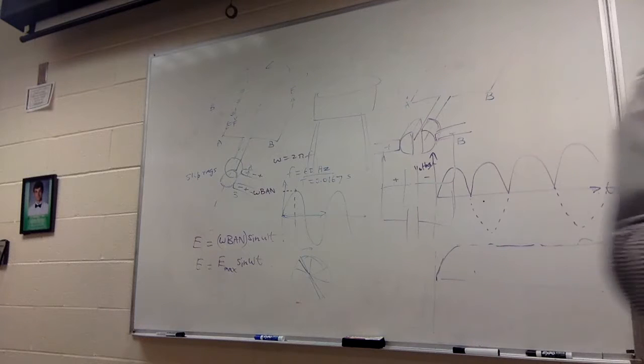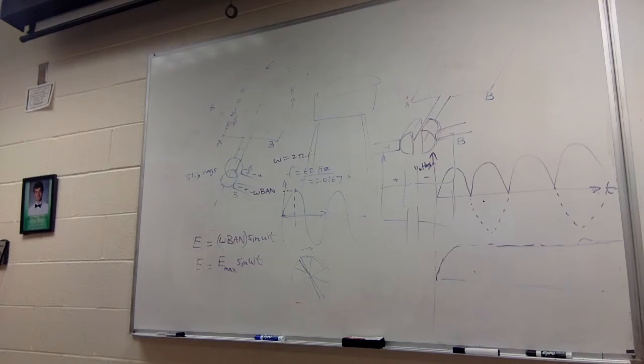Do you see that capacitor sitting here? The purpose of that capacitor is to smooth the output. And we're going to talk about transformers right now. So that is the capacitor which actually makes it smooth. Now, a bigger capacitor will make it better. So good adapters will have better, larger capacitors, and the capacitors are required to make the output smooth.